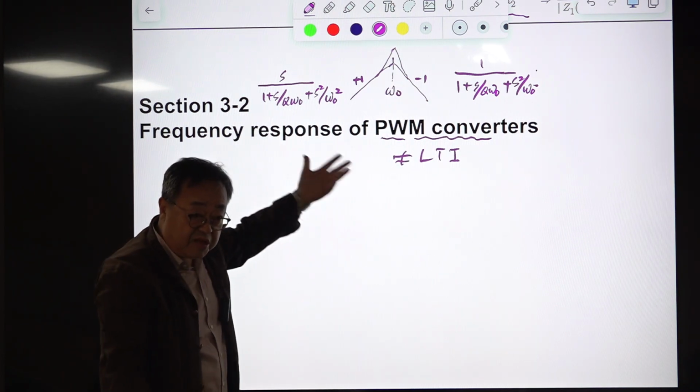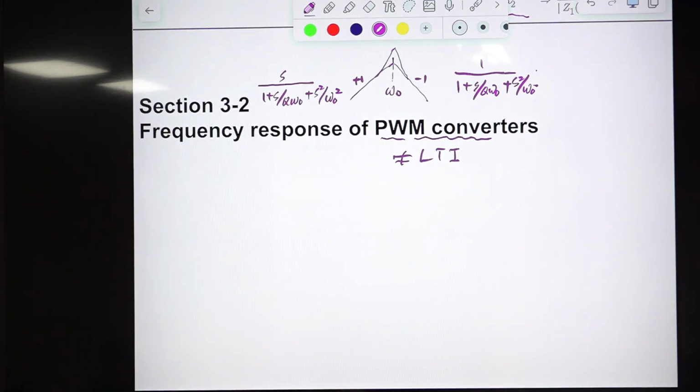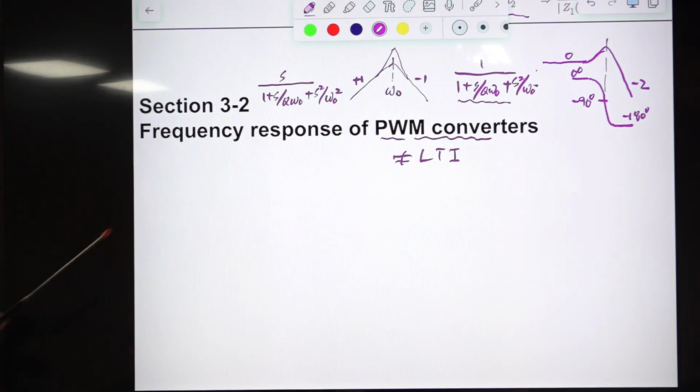That is true when this asymptotic plot is symmetrical with respect to this axis. But if that is not true, then the phase at the peak is not 0. Suppose this one is this transfer function. Then it starts from 0 dB, and it goes up and has some peaking like that. And this is minus 2 slope, 0 slope. The phase at these frequencies, this one is 0, this one is minus 180, and the phase at this point is minus 90, not 0. 0 is here. So just seeing this peak does not guarantee 0 degrees of phase. If everything is symmetric, then it makes sense.